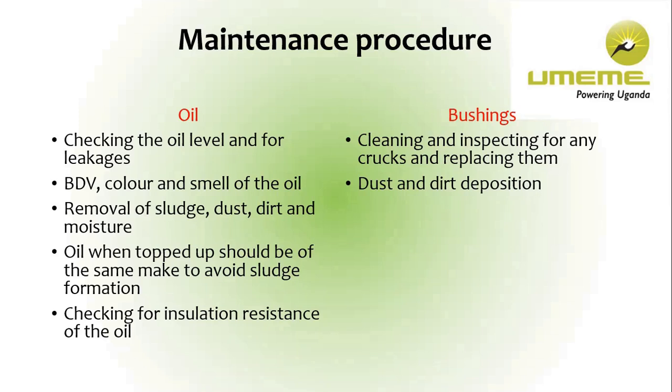You also make sure that before replacing the oil, the new and old oil are of the same make. If you bring in a different type of oil, then it might lead to sludge formation. We also check the insulation resistance of the oil. It has to be as high as possible to maintain the insulation between the windings.